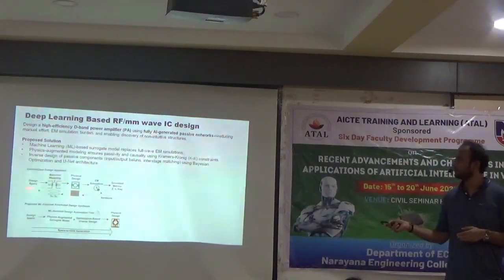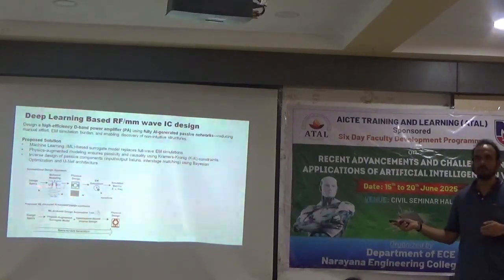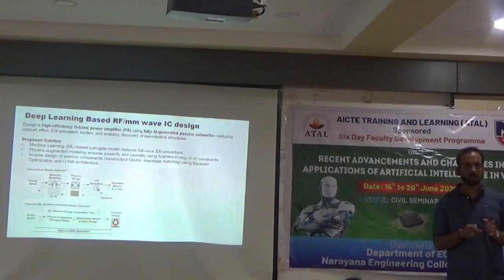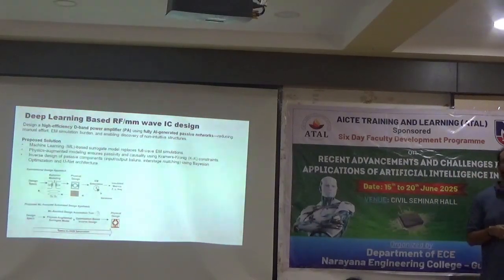They started from the design specs and did the behavior modeling of the different blocks, then the physical layout, and then they fed it into the simulation. So this is how they start with the design spec and go to the physical design. The end goal of the AI is to reduce the time the engineer spends optimizing the design.